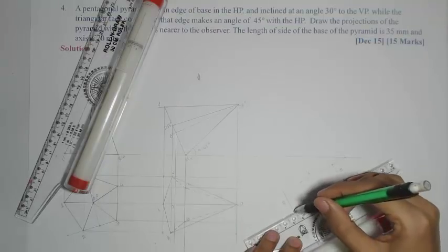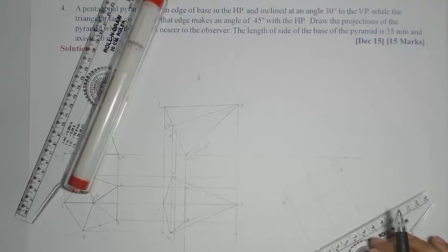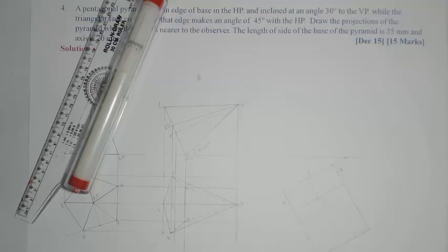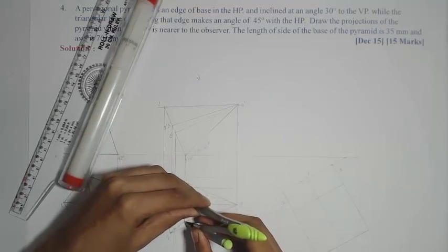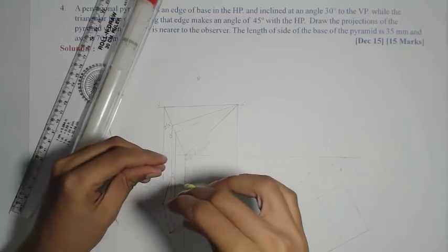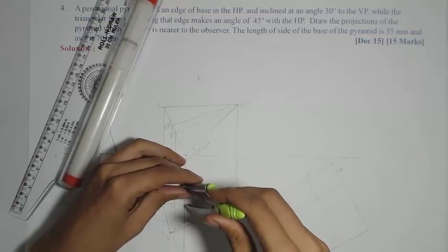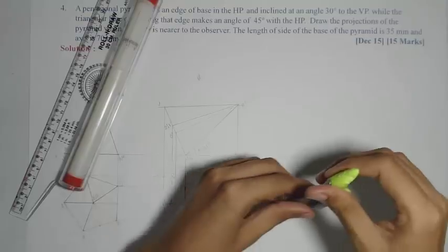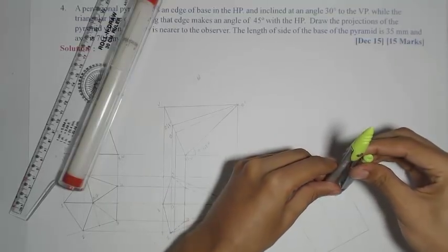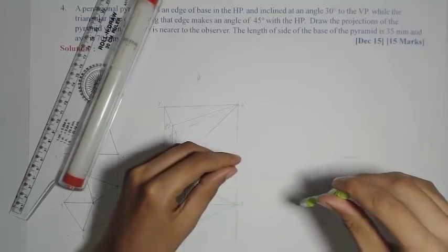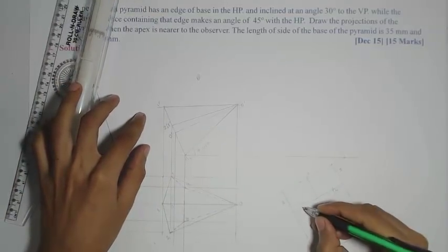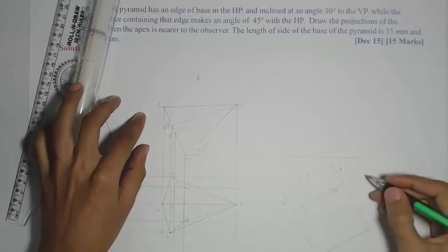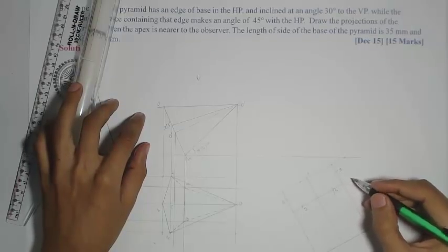So here we can mark that parallel line. So this inclination will also be 30 degrees. Now to get 3 and 4 from this center point, we can get the distances for marking 3 and 4, which will be the same on both sides, for 3 as well as 4. So with that distance, we'll mark 2 arcs to get 3 and 4. The point nearer to 5 is 4 and the point nearer to 2 is 3. So we have marked all the 5 points of the base.